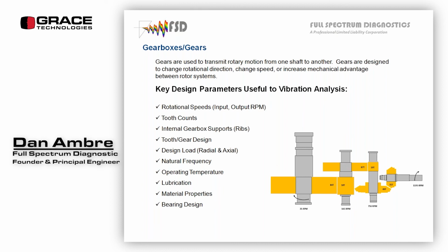We're going to take two sets of data. One set of data is going to look at the health of the bearings on the inside, and we want to take those axial, horizontal, and vertical.